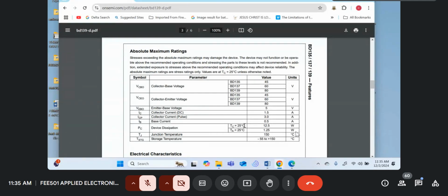Now, as you continue to pass current through the transistor, it warms up, and you can get the power by just multiplying the current through the transistor times the voltage across the transistor. That gives you the power the transistor is dissipating inside the circuit. But since the metal part of the transistor is so tiny, the temperature will start to increase very rapidly.